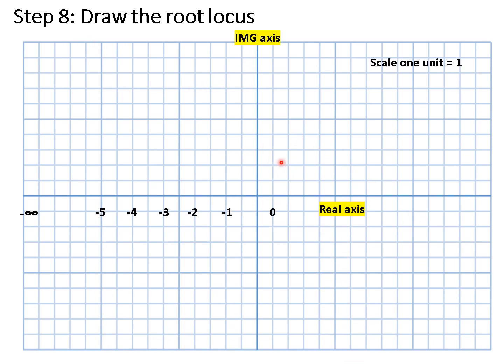X-axis is the real axis and y-axis is the imaginary axis, and we have some pole points, from 0 to -5, which will go along till infinity. So in the given system, the number of poles given is 3: one is at 0, another at -3, and the other one at -5. The first thing that we need to do is find where the root locus exists.